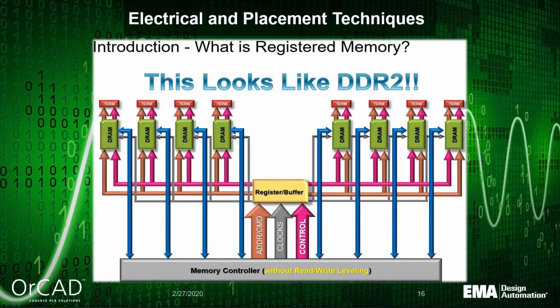The DDR4 component placement looks a lot like the old DDR2, DDR3 in placement of termination. Now, the termination takes up much more real estate, adding costs for the components. Routing becomes more important. Remember, we're routing in picoseconds, no longer in nanoseconds for time.